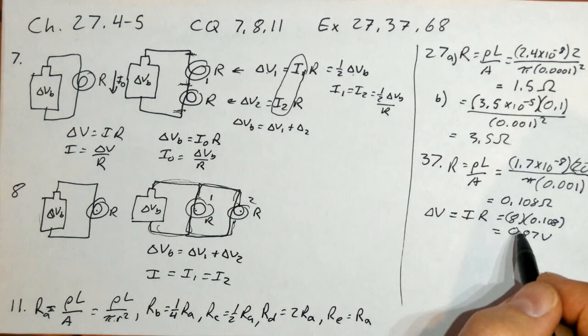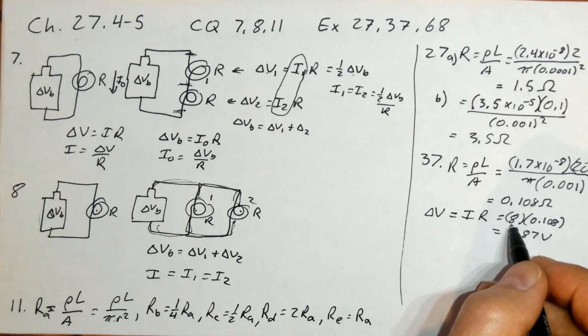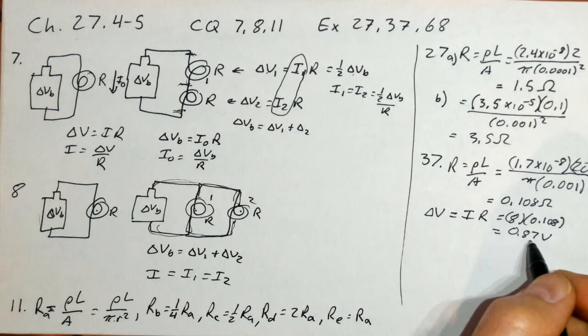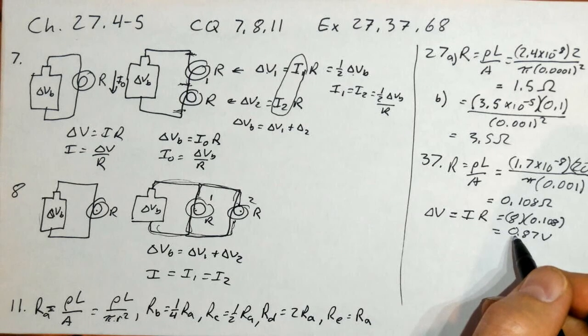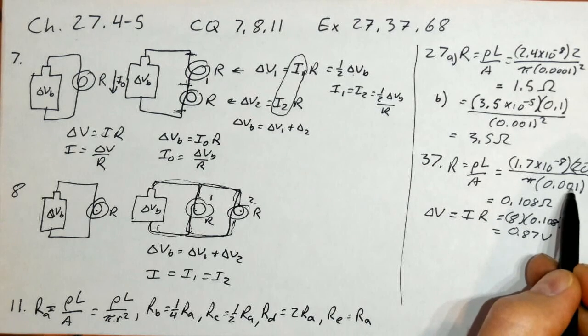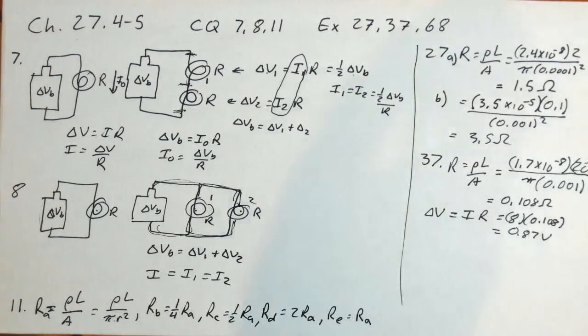Now, 8 amps is actually quite a large current, and so you wouldn't want that much current flowing. The bigger the current, the bigger the drop. And if you have something really large, like let's say a hot tub, that draws a lot of current because of the heating element, then the voltage drop, especially if you have it somewhere outside, a distance from your house, could become problematic. And that's why most things that draw a lot of current actually have even bigger wires, like really thick wires, upwards of 3-4 millimeter diameter, still made out of copper because it's the most useful material there.